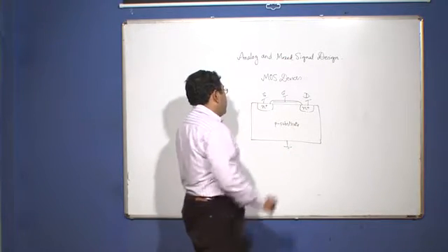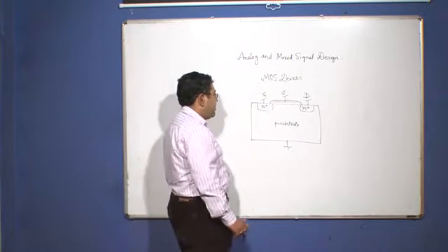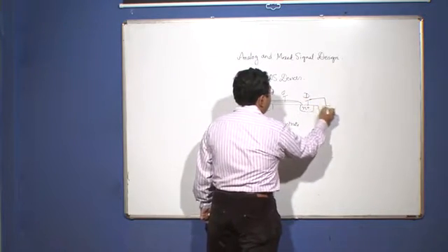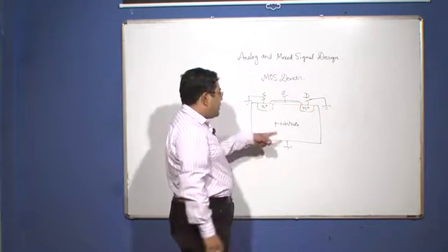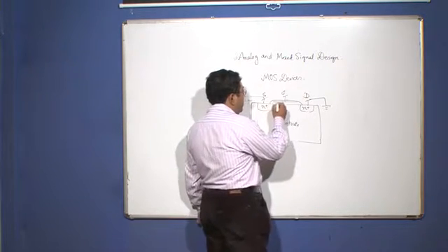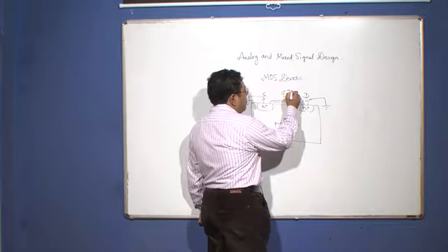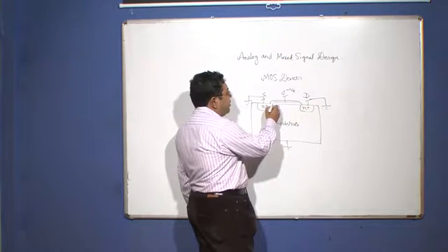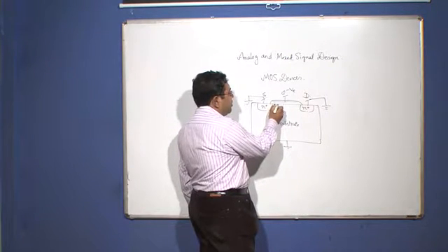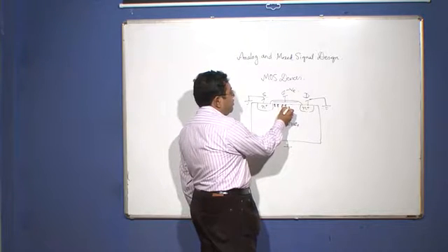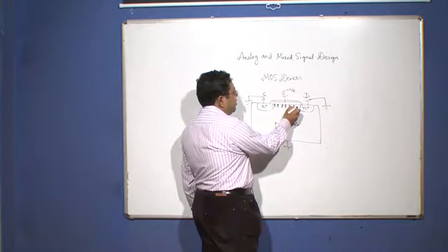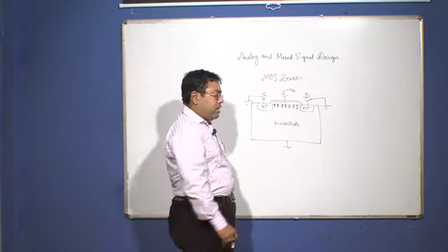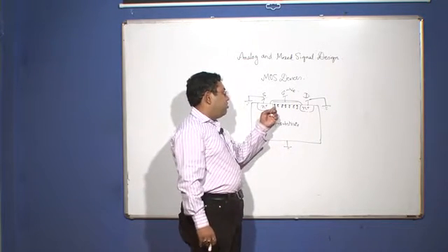Now, if you want to analyze the behavior of this device, if you connect the source and drain to ground and apply a potential to the gate and keep the bulk in the ground, then if this is a negative potential, once you apply a negative potential, it will attract the holes in the p-type substrate towards the interfacial layer between the oxide and the substrate, and you will see that an accumulation of holes has been formed.